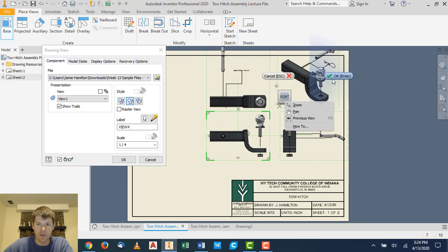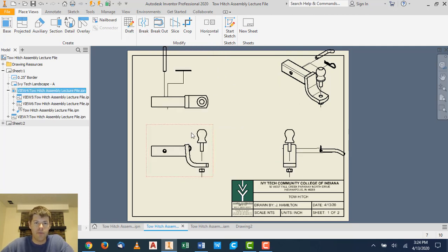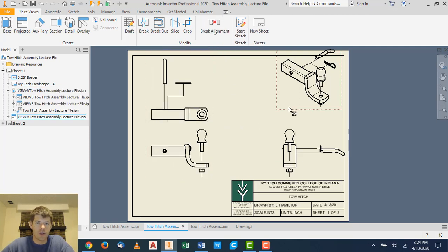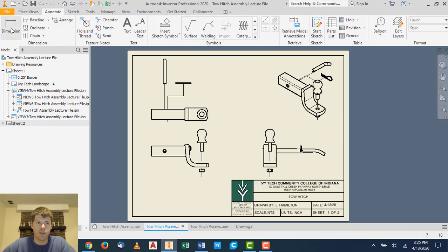This seems like what you should do, right? Because this is what I taught you to do for individual parts. But I get people that do this all the time for the assembly models. This trick of orthographic drawings is only used for individual parts. Don't do it for an assembly model like this, because it's really kind of useless. Assembly views are just to visualize the object, so this does not do anyone any good. Also, you typically don't dimension assembly drawings. Don't do this, okay? All you really want to see for the assembly is visually what it looks like.